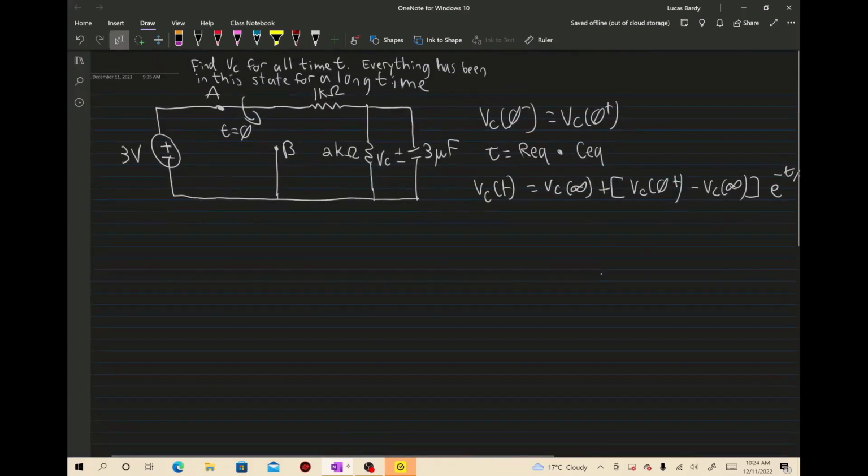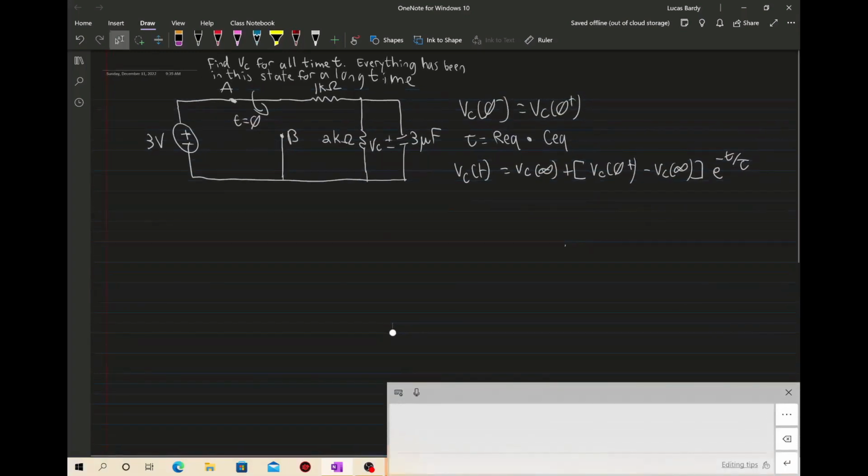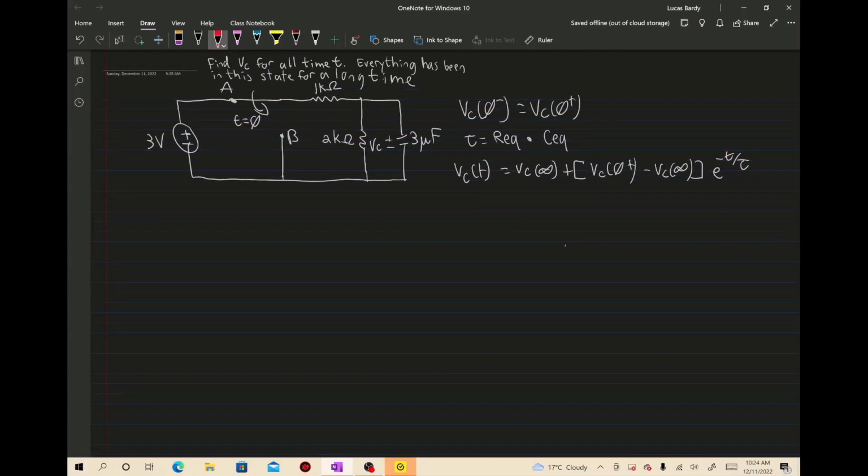Now, as we can see here, we have a simple RC circuit with a 3-volt voltage source, a 1 kilo ohm resistor, a 2 kilo ohm resistor, and a 3 nanofarad capacitor. And on this side, I have here our basic equations for a start, which you should always just write down. We got these from the rules mentioned in the first part of the video. You should always write these down to get the extra points.